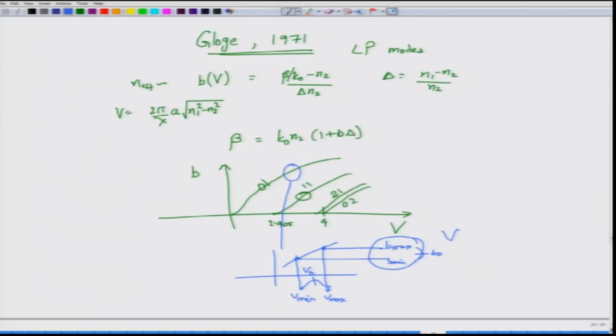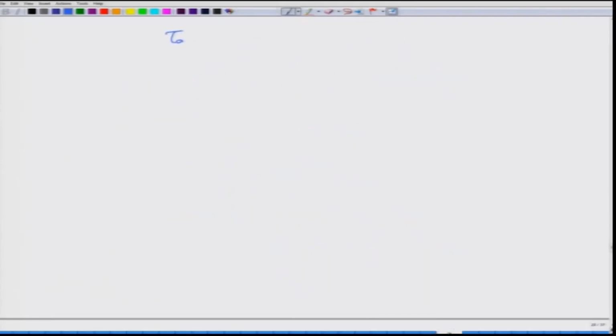Okay. But we do not normally do it in that way, we actually go back to the delay tau g, that is that we express, and this tau g we write it in terms of the simple d beta by d omega that we already know, which is of course beta 1 parameter. You can adjust this expression d beta by d omega by differentiating beta with respect to k naught and then